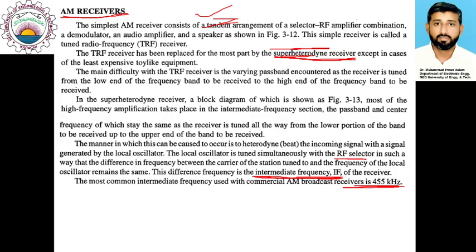Using an intermediate frequency stage provides significant flexibility in hardware implementation, because the number of channels used can be combined at the intermediate frequency stage, and we have good signal processing hardware available for this 455 kilohertz based intermediate frequency.